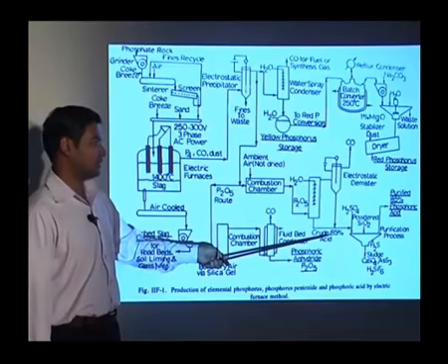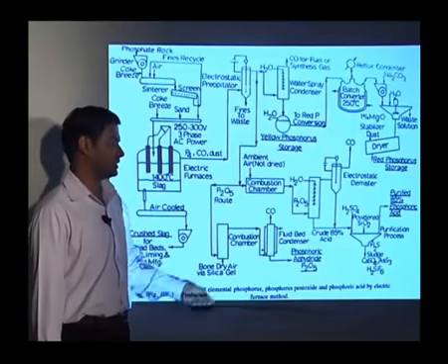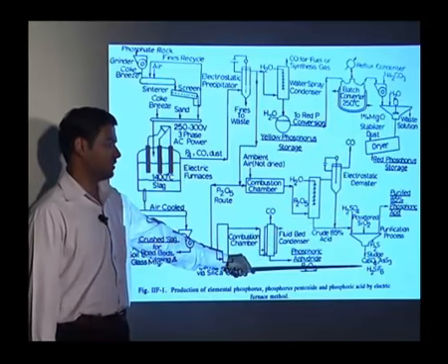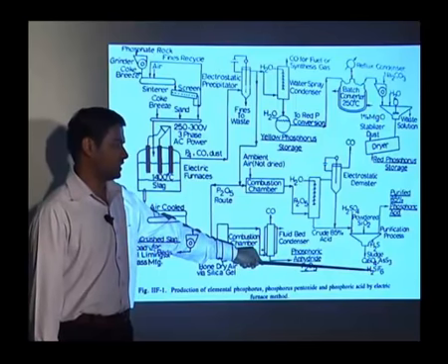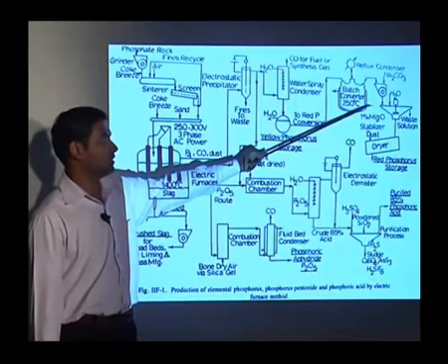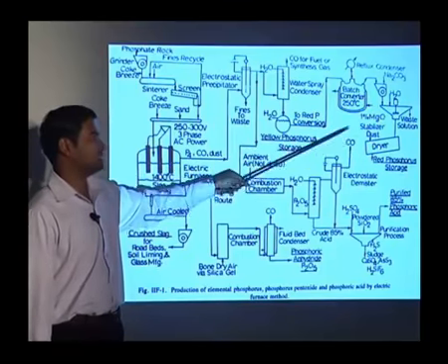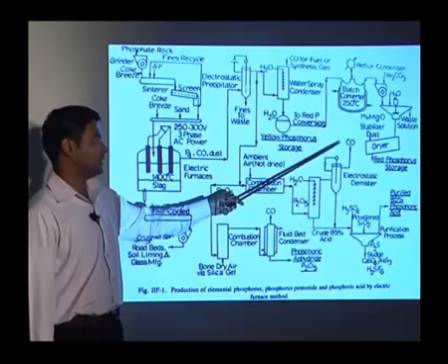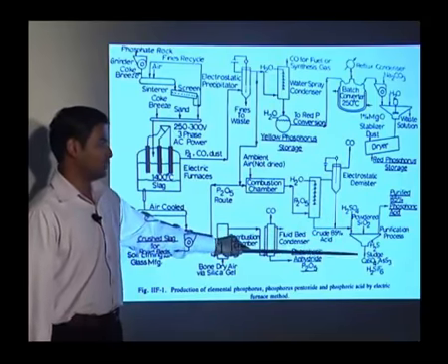That phosphoric acid we store as purified 85% phosphoric acid, and then there is sludge which will have CaSO4, the arsenic and the silicates. Here also Na2CO3 is required to remove the arsenic, which is the impurity in the final product, and here we can also add lime to remove impurities such as the arsenic.